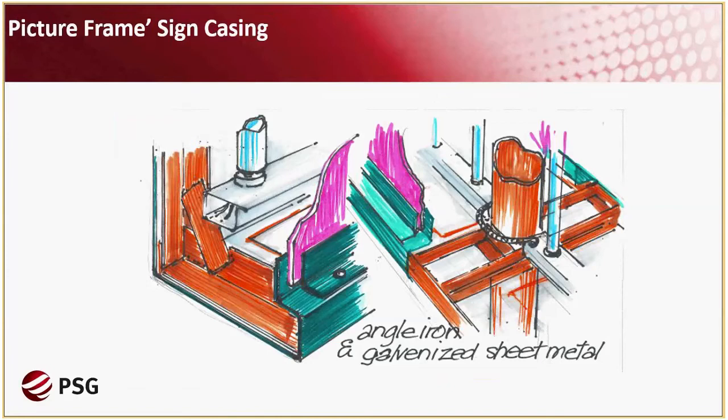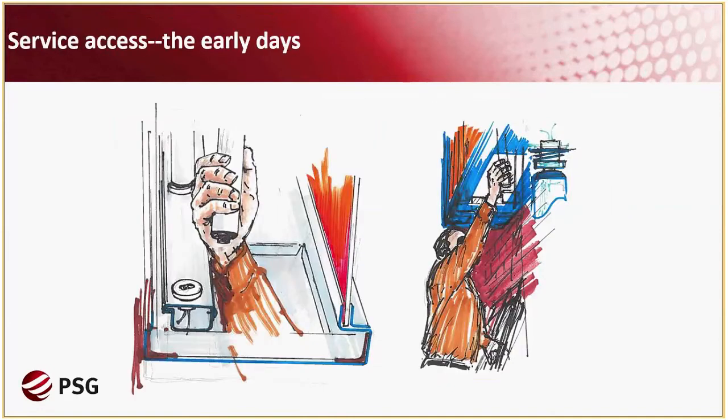You had a steel structure that would support all those components and ballasts, and it was wrapped, and that's why it was called a casing at one time, because it enclosed that structure. And the plastic substrate to face the plastic was held on the outside and retained with the formed galvanized angles. The same was repeated, of course, for a double-faced version.